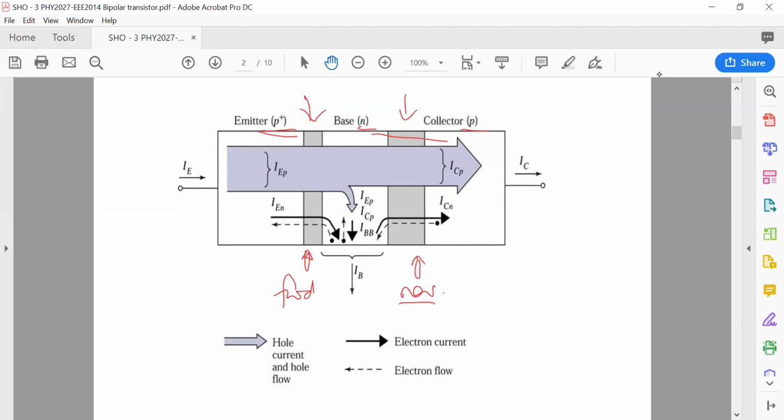I have to remind you, one thing this diagram does make clear is that both of the charge carriers are important here. This is unlike the MOSFET, where we're really looking at one type of carrier being important for the output characteristics. Here in the bipolar transistor, both types of charge carrier are important, both the electron and hole flow.